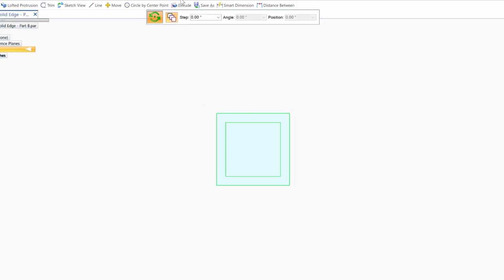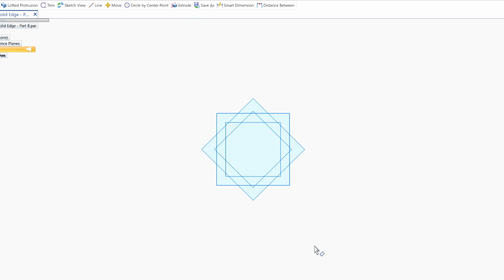Now I'm going to highlight the shape. I'm going to say rotate 45. Then I'm going to go to the center of this rotation here, click, go horizontal, and then move 45 degrees, click and get escape. This is how you create the same copy but rotated 45 degrees.